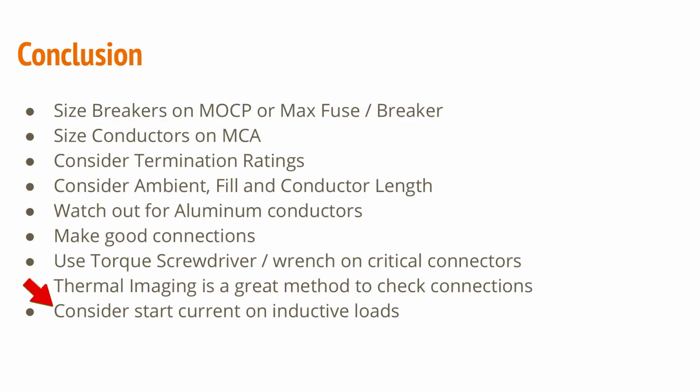And then consider start current on inductive loads, which means that just when you're working with an inductive load, a motor load, just remember that your start current is going to be higher. Now, obviously, if you're following the manufacturer guidelines, then you're safe. It's when you get into really big stuff with built-up systems that aren't engineered, that now there's quite a bit more engineering that has to go into the design of the electrical system.